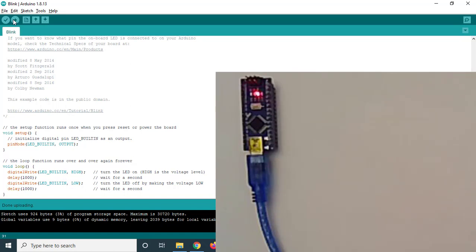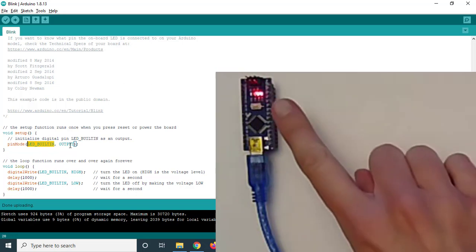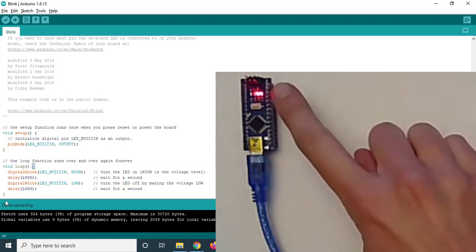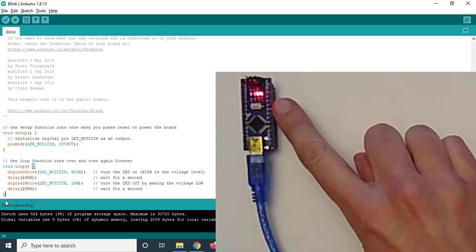All right, now notice my code is blinking. So what happened? Well, first off, we did this void setup. So it is setting up, hey, I need to initialize my pin mode. And so my pin mode here is basically saying I need to do something. I need to establish that I'm doing something to my built-in LED. Okay, that's this thing that's blinking right here. It does this one time. Okay, then the loop is doing something over and over again. So right now, it's on a second, off a second, on a second, off a second.